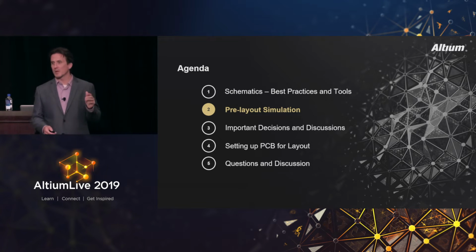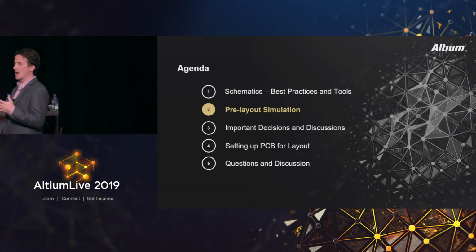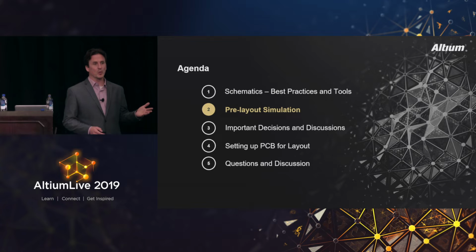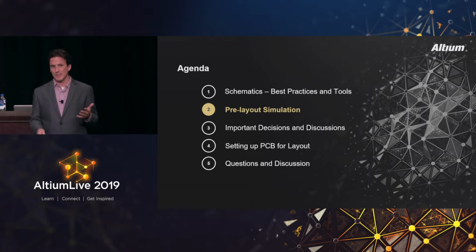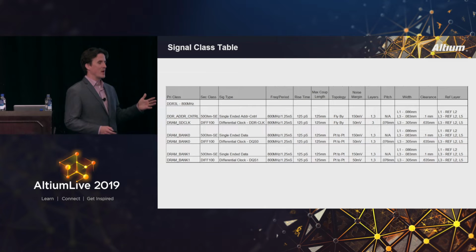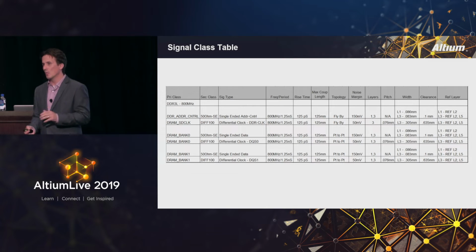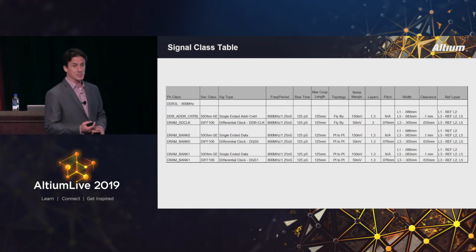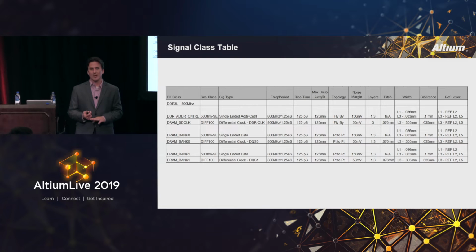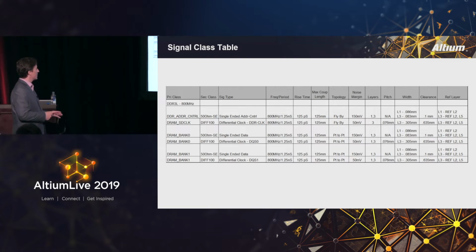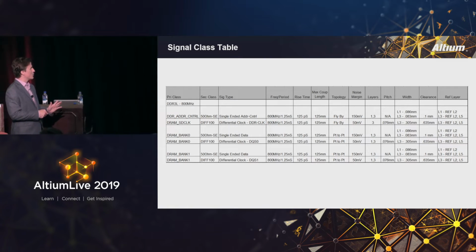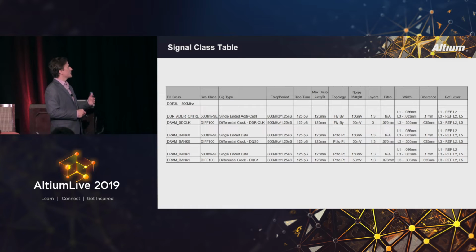All right, so we're into pre-layout simulation, and I'm going to talk about a couple of tools and some of the methods that I use for pre-layout simulation. One of the things that I do previous to any layout is a pre-layout simulation of my critical buses. And the most important thing in here is the rise time, but interrelated to the frequency. Taking the rise time, I'm doing a pre-layout simulation.